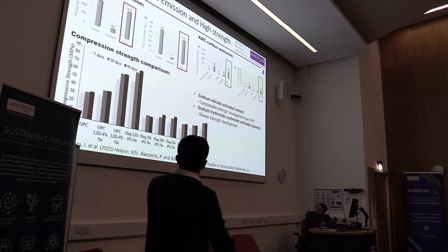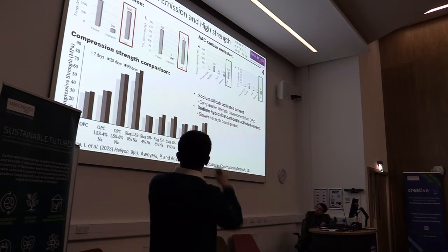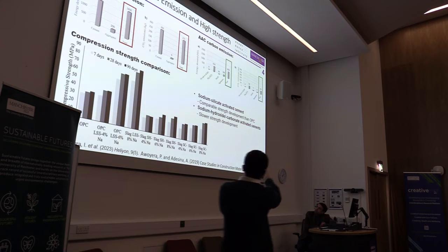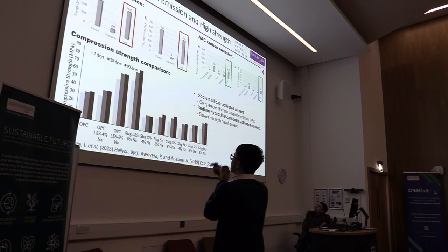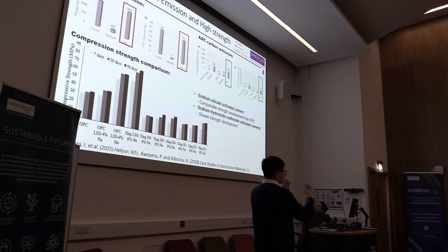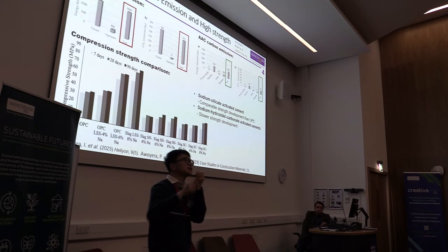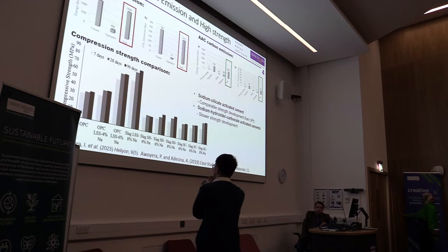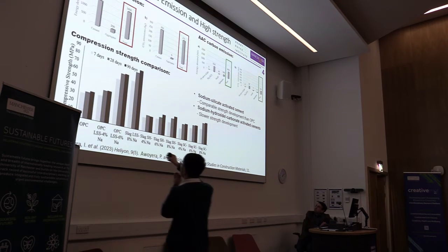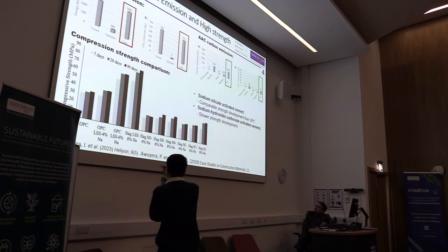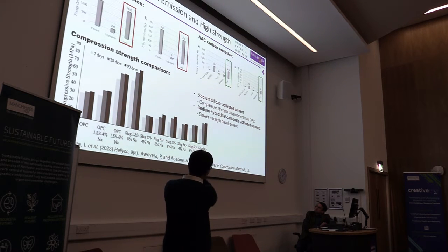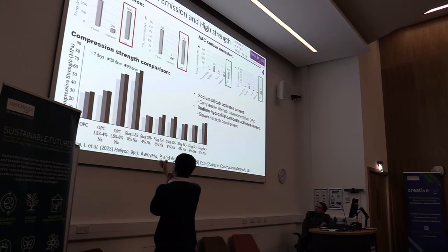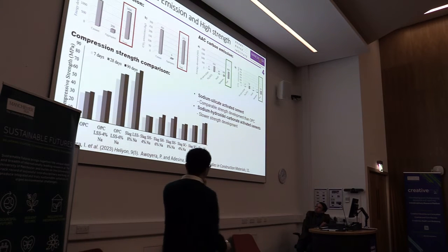As you can see, this is the advantage of alkaline activated cement. It reduces a lot of carbon emissions compared with conventional Portland cement, and it also saves a lot of energy cost. Another advantage is high strength, especially when using a sodium silicate activator. The strength development of alkaline activated slag cement produced with sodium silicate activator is comparable to, even better than, conventional Portland cement.